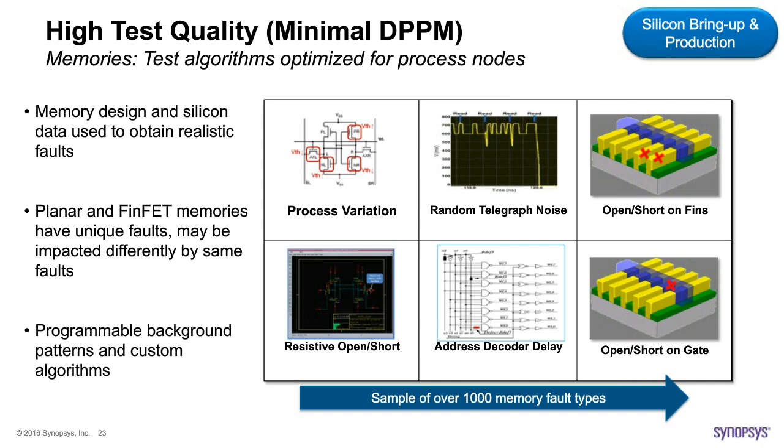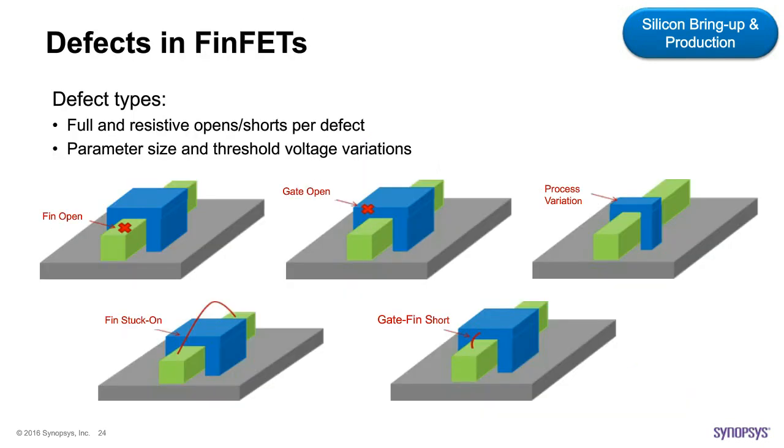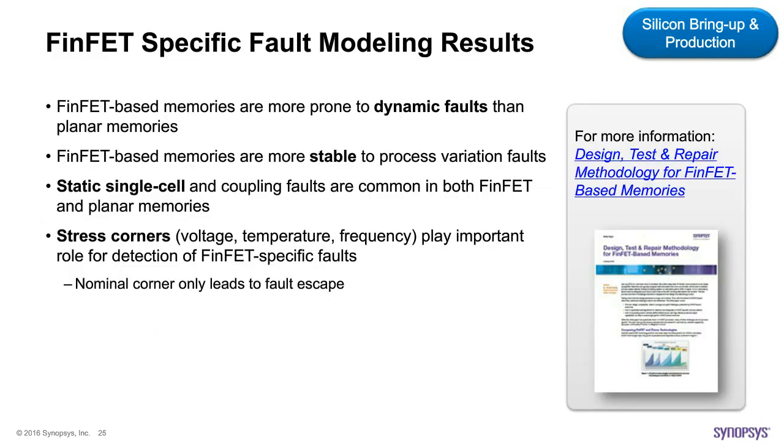And we found out that there are several new types of failures that are happening in the FinFET domain that we did not see in the past. Therefore, we had to increase our fault models. We had to increase the coverage of our algorithms to contain the specific failures such as these gate opens, the fin stuck-ons, the fin opens, which have manifestations that are not similar to the planar technology, that are newer in terms of types. In fact, they are newer in the sense that they are more dynamic in nature, given the fact that the transistors are three-dimensional.